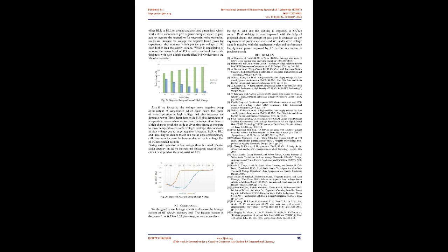Reliability issues and improved circuit at high voltage of negative bit line write assist. As technology is shrinking, more and more transistors can accumulate on a single die, but the problem occurs because static leakage increases compared to dynamic leakage. So to decrease the static leakage we need to decrease the supply voltage. But due to decreasing the supply voltage, stability problems arise in memory, and stability also decreases due to the conflict between memory read and write operation. So to overcome this problem and increase the stability of the memory cell, we require some assist techniques.